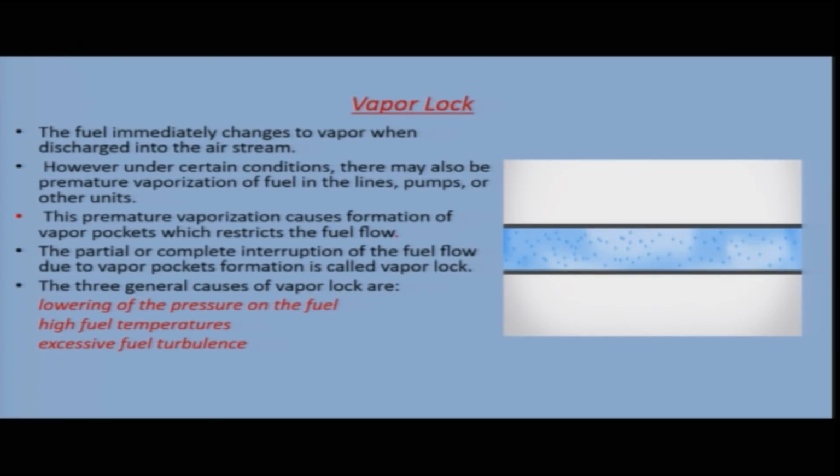Now, what is vapor lock? The fuel immediately changes to vapor when it is discharged into the airstream. As soon as the fuel is discharged into the airstream, it vaporizes. However, under certain conditions, the fuel may vaporize prematurely in the lines, in the pumps or in other units.